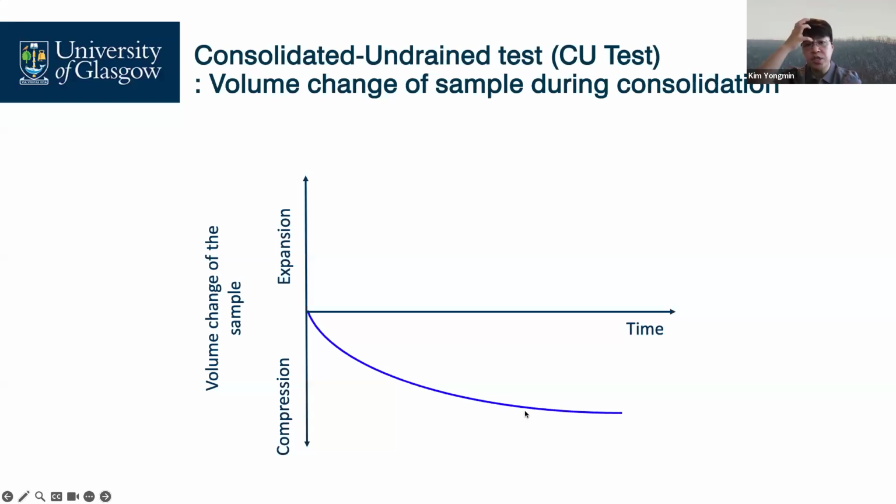In the shearing stages, our drainage valve is closed. How can we measure the soil volume change? Cannot. Cannot.